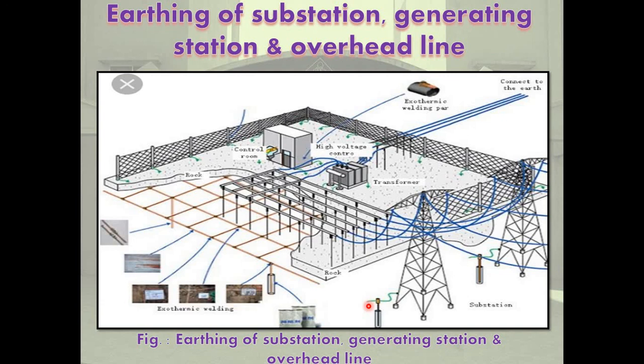Use circuit breakers with pre-insertion resistors. Use surge arrestors between phase and ground to limit switching surges. Use surge suppressors.